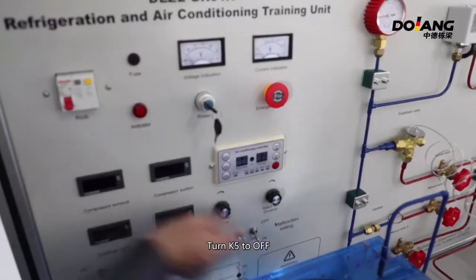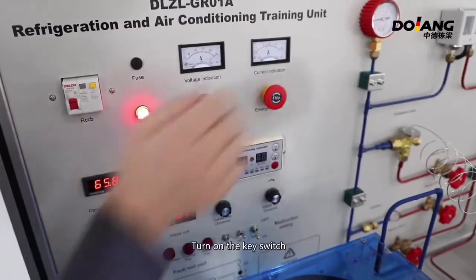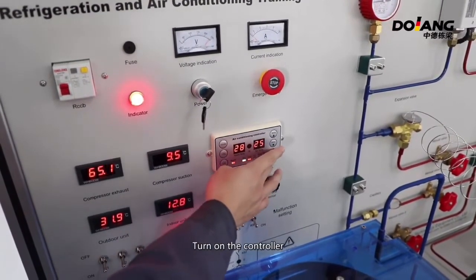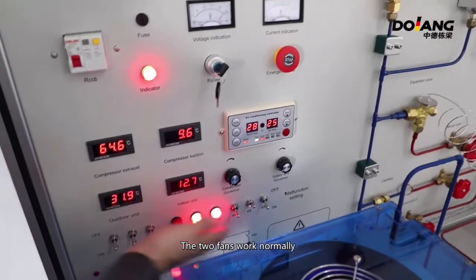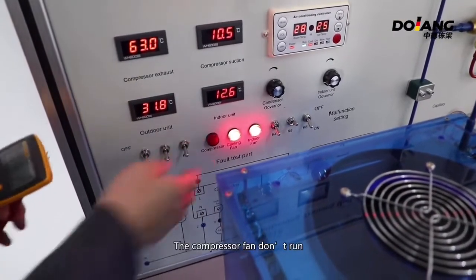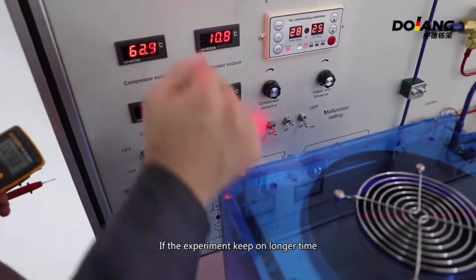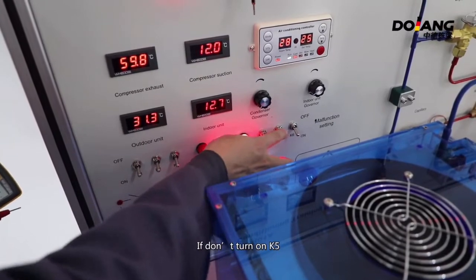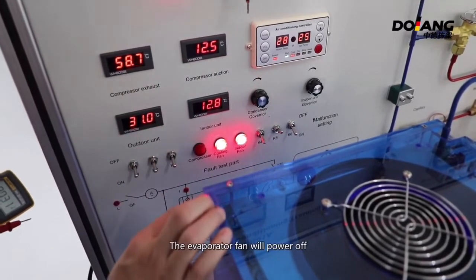Now do the fifth fault experiment. Turn K5 to off. Turn on the circuit breaker. Turn on the key switch. Turn on the controller. The two fans work normally. The compressor fan doesn't run. If the experiment keeps on for a longer time and you don't turn on K5, the evaporator fan will power off.